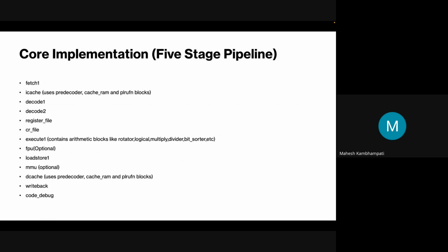Then execute is where the real execution happens, and contains blocks like rotator, logical, multiply, divider, which simply execute the arithmetic functions or logical functions. And there is the FPU and MMU, which are optional, but we can include them.